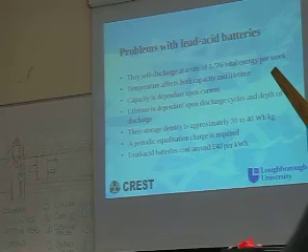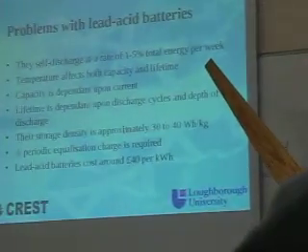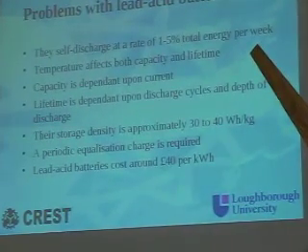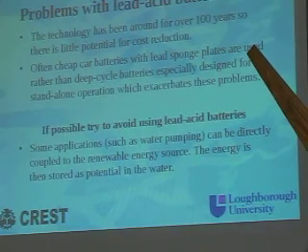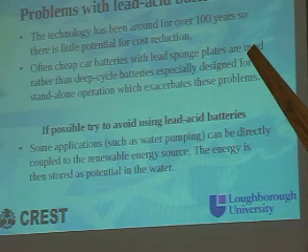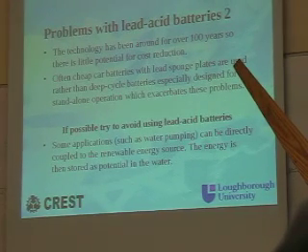They're very heavy, so storage density is not very good. With open-vented lead-acid batteries, not the sealed ones, you need to equalise them, so make sure that all the cells are the same voltage. They cost around £40 per kilowatt hour, and they've been around for about 100 years. There's not much chance of the cost coming down dramatically. But they are very obtainable. They're easy to obtain in lots of places.